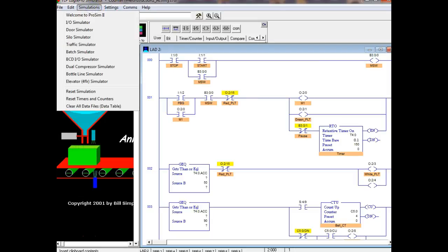Now, does that save time? Yeah. Probably not. I thought you said it doesn't have to scan as much stuff. Well, unfortunately, the scan is not the number of rungs. The scan is the number of stuff in the whole thing. So every one of these things counts. And what's nice about the Allen Bradley documents is they show you the time every one of these instructions actually takes. So it's the number of instructions in your program that determines the scan time, not the number of rungs.